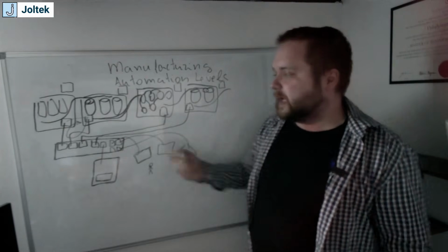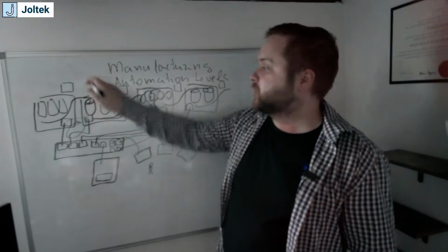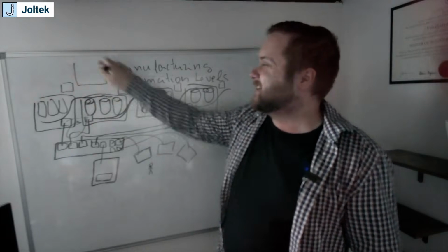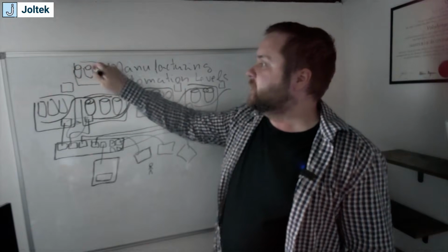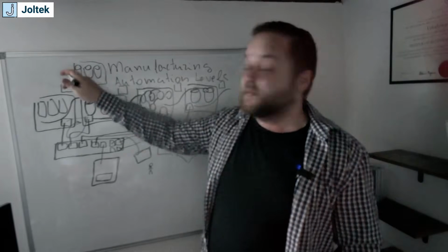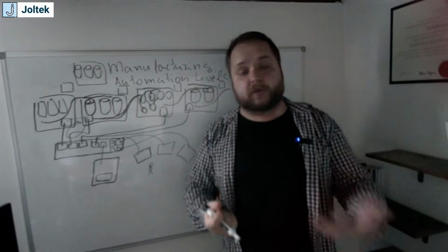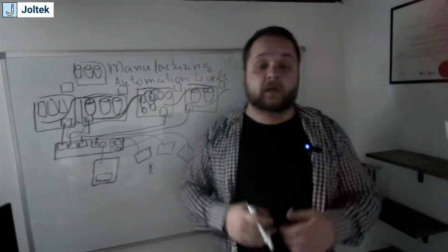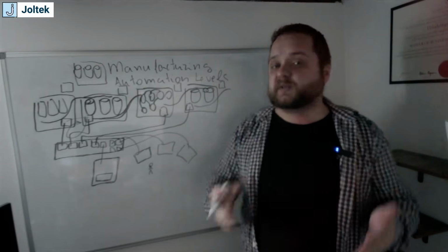So usually the exercise is during commissioning, if you, for example, add a new system, right? We've talked about adding maybe a second set of tanks here at the very top. The engineers that are commissioning the set of tanks are going to need IP addresses for your PLC, for your HMI, for your VFD if they're on the network, for your load cells, right? So they're going to need a range of IP addresses that they can allocate to those specific devices.